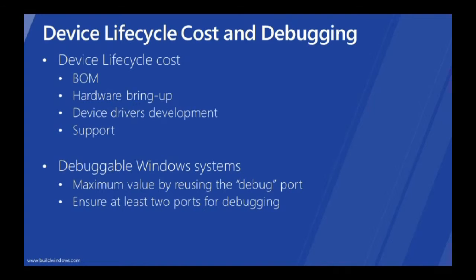For example, if a cost-reduced machine has a scenario that uses the debug port for the customer scenario, then that scenario is undebuggable. If the scenario is undebuggable, that machine is also undebuggable, and this becomes a design failure. A good example is using the only USB 2 OTG port for any of the following: IP networking, mass storage, keyboard, mouse, charging, or docking. But this exact same situation can occur with any type of debug port. It's not particular to USB 2 OTG.